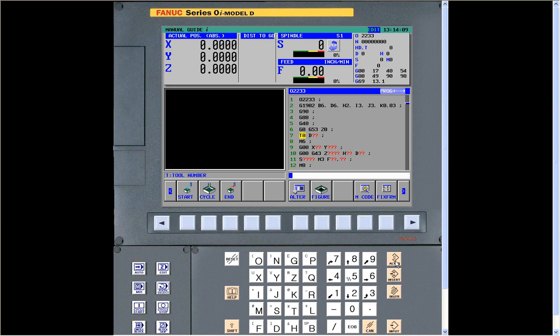So 8, arrow over to the D number, which is the cutter compensation number, 8 again. And see, as soon as you do that, with that line over here, it tells you what tool we've called up. It's a face mill. All right? So then we go down.